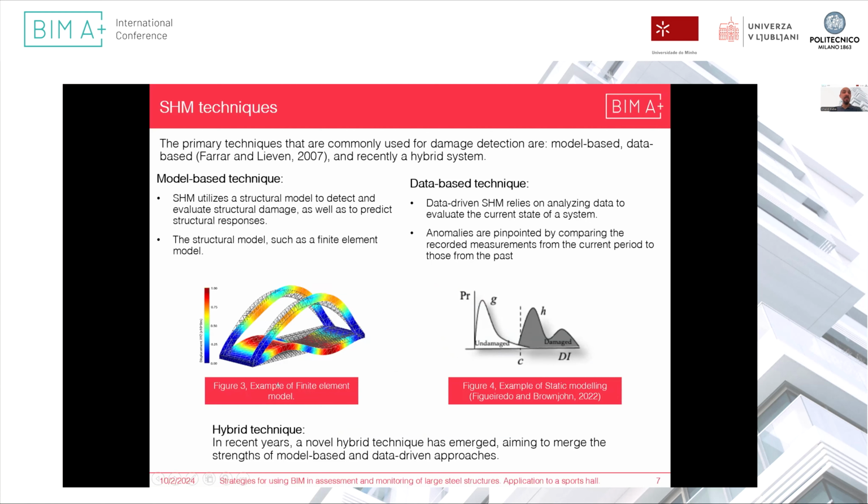For the model-based approach, we need to develop a model of the physical structure, either a finite element model in our case or a modal model, which deals with vibration of the building. In the database approach, it will compare the data of the damaged part with the undamaged part, and any deviation from the undamaged part will be considered damage or developing damage.